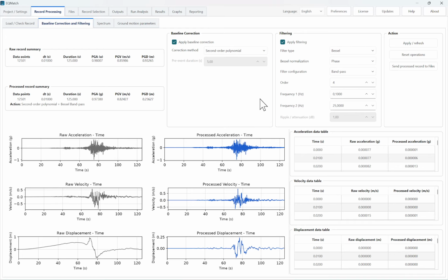Earthquake acceleration records often need to be pre-processed before they are used directly in engineering analysis. One of the main reasons is that raw acceleration records may contain small sensor-related offsets, low frequency trends, or numerical shifts that occur during or after recording. These small errors may not be very obvious in the acceleration record itself.